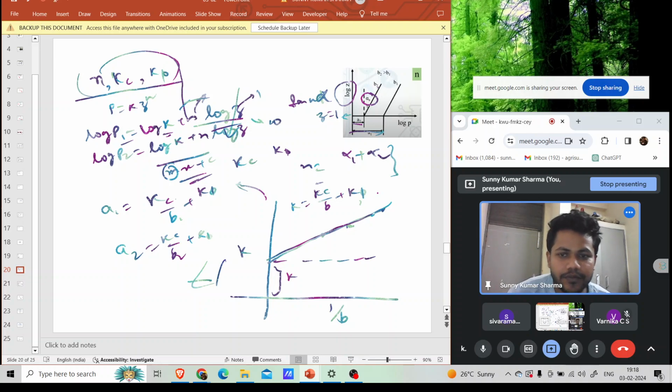So from the values of the plates, we got some K values, and this will relate to Kc and K phi. See, this intercept is our K phi and X is our 1 by B for different B, meaning for different plates. For plate 1, we will have 1 by B1.